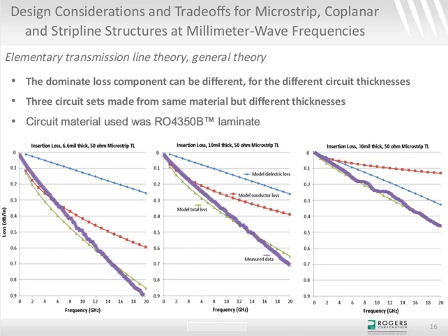One thing to note there is overall there's definitely more insertion loss, and that's what happens when you go to a thinner circuit. In this case, the reason that happened is because there's more conductor loss. So in general, a thinner circuit is going to be more sensitive to conductor effects, and in this case we're talking losses. A thinner circuit is going to be more sensitive to the conductor loss and whatever changes conductor loss.